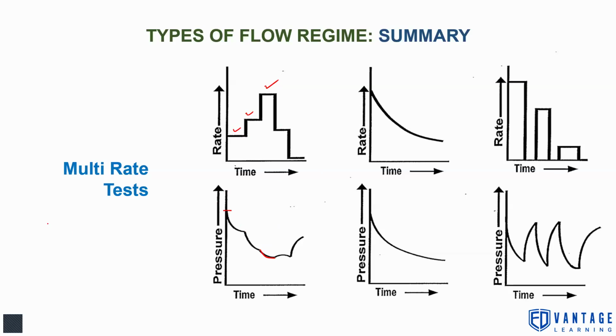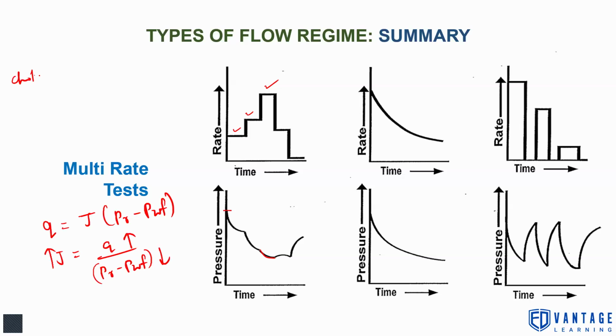So whenever you look at the IPR equation, Q is equal to J, the productivity index, into P reservoir minus P bottom hole flowing pressure. So J would be Q by P reservoir minus P bottom hole flowing pressure. For J to be maximum, your Q should be higher, and the denominator, which is the drawdown, should be lower. So we do a multi-choke study, or multi-beam study, where we have choke sizes 1, 2, 3. Assume choke size is increasing towards the bottom.